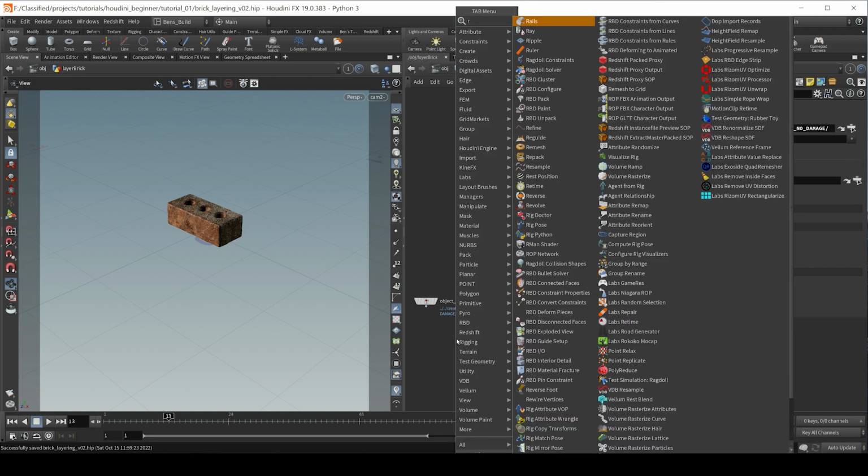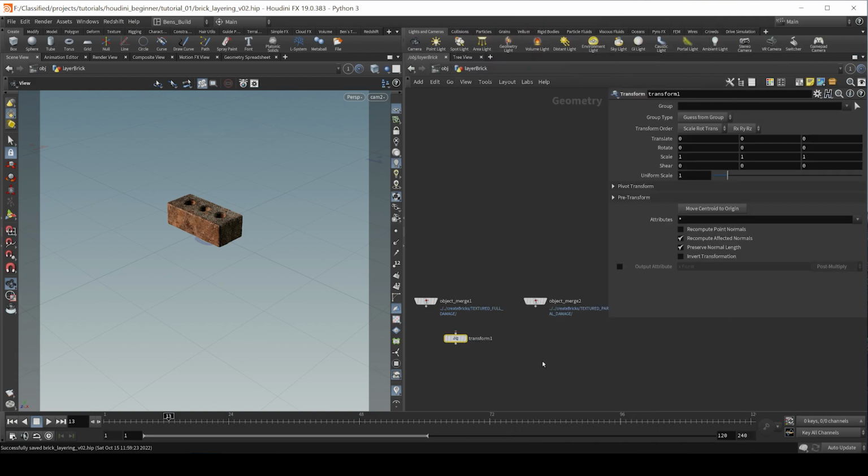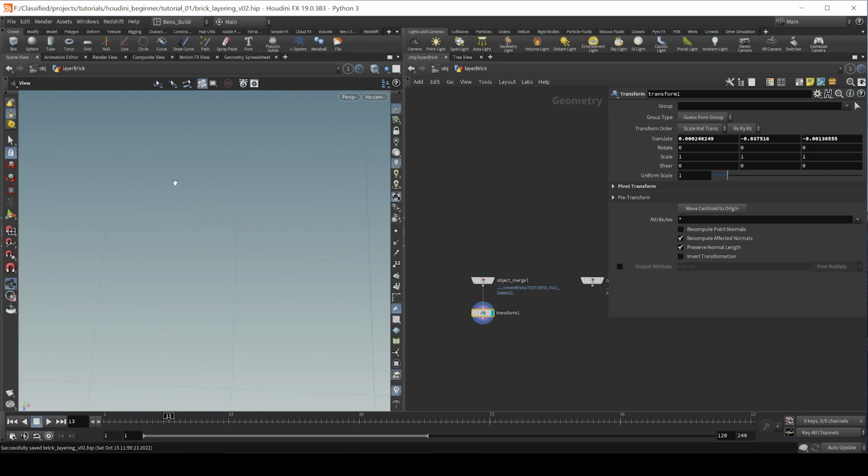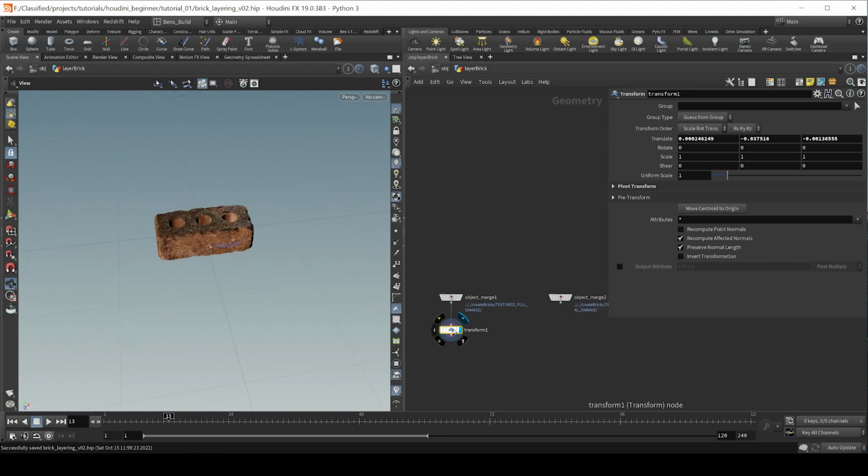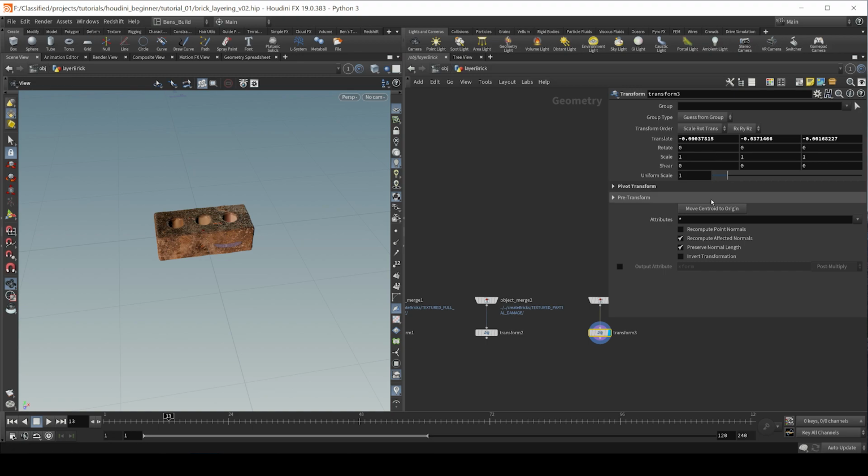The next step, what I'm going to do is transform these bricks to their centroid. If I hook up a transform, move to centroid, now it's in the center of the brick. To zoom in on a piece of geometry, if your mouse is hovering over the viewport, you can hit space G, and it will zoom right in there so you can navigate easily. I'm going to Alt drag, click that just to make sure it's at its center, and here as well.